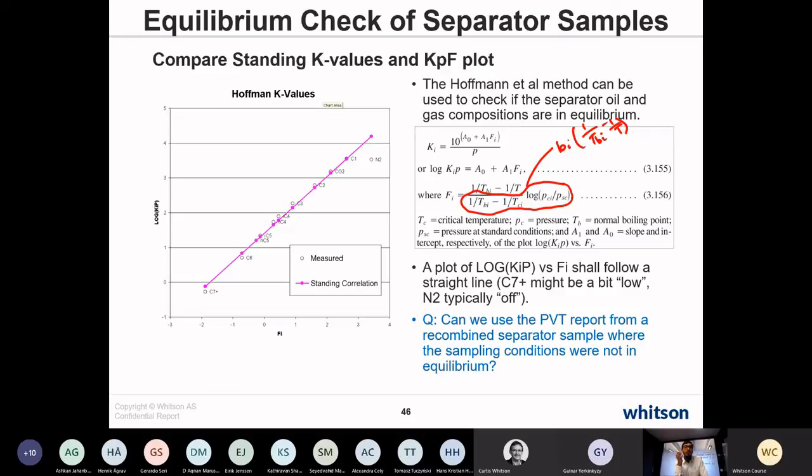So we knew the well stream composition reported by the PVT lab, and we had all the PVT data measured on that well stream composition. With that known composition, we used the data for EOS model tuning and developed the EOS model for all the 60 plus samples.